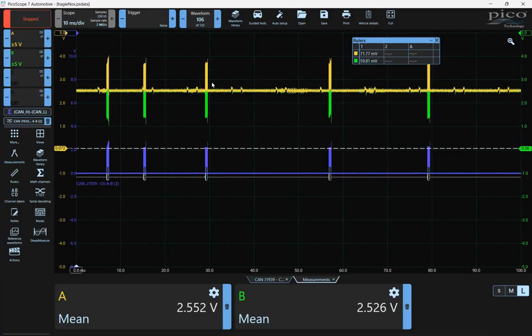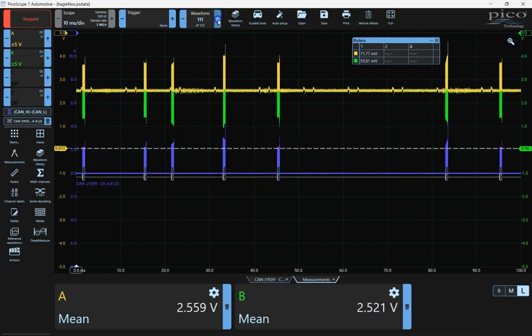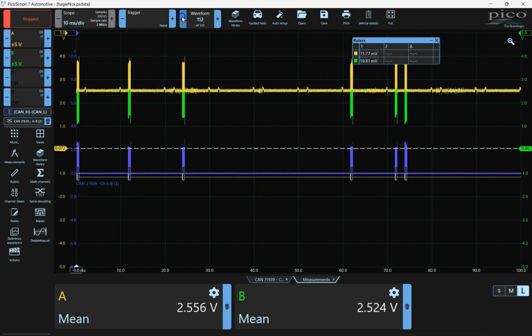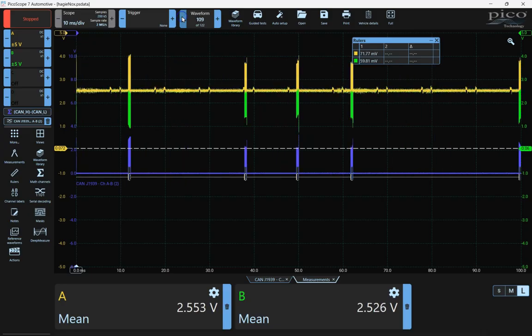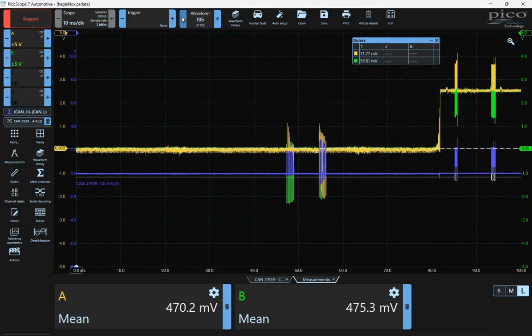So with the oscilloscope being able to see that waveform and to watch this drop here that we saw, as you can see, this happened quite frequently, but it was very, very short duration that it occurred. We found one particular spot in the harness. He got really lucky and he grabbed right where it was. And when we moved it around, it wasn't a short to the frame of the machine anywhere, the engine block or anything like that. This was a wire to wire short.